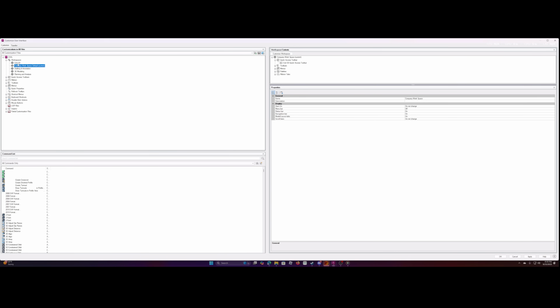So here, now that we have this company workspace default, right? We know that we went to ribbon, we went to tabs, and we had created one that says our company tab. So what we want is to create our own panel. So these are panels. This is our palettes panel, our explore panel, optimize, ground data, create design, right? We want to create our own.